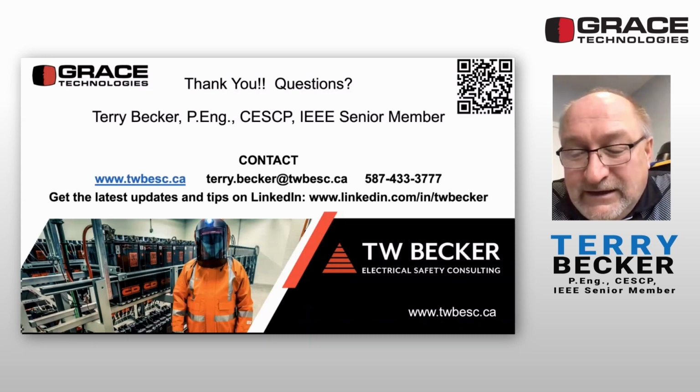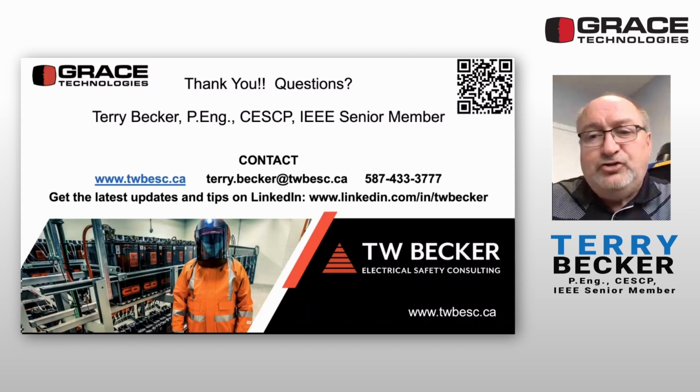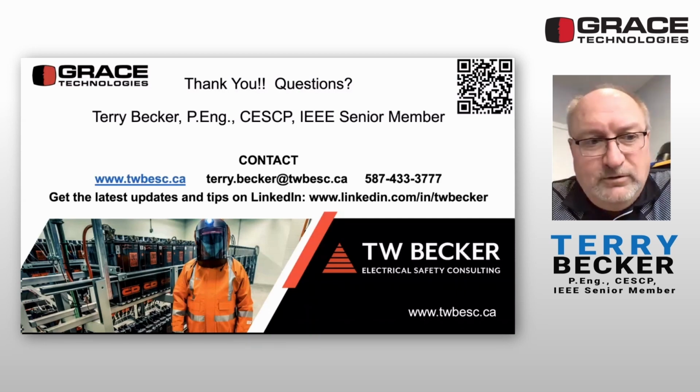Let's see. Does CSA have any guidance on PPE requirements for 1500 volts DC with photovoltaic? Well, yeah, it does. But 70E and Z462 are never going to provide you direct information. They're going to say do an arc flash and shock risk assessment related to the work task being performed on the electrical equipment, right? So for photovoltaic farms, we can get up to 1500 volts DC at the combiner box. Well, okay, great. It's no problem. It's no problem until a work task is completed on the combiner box at 1500 volts DC.